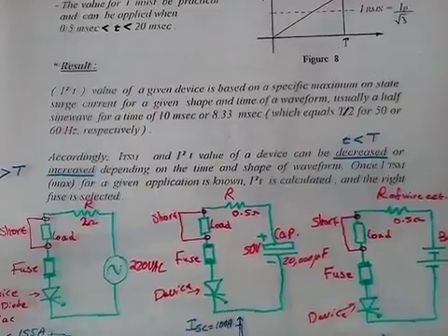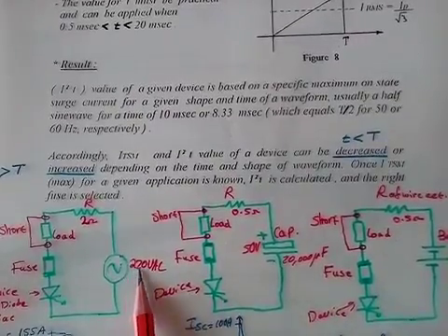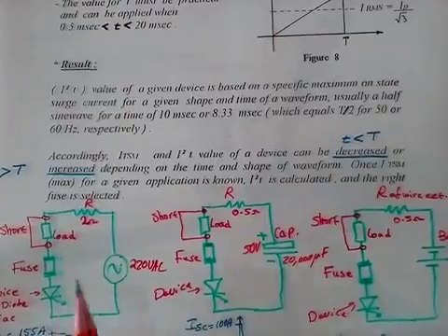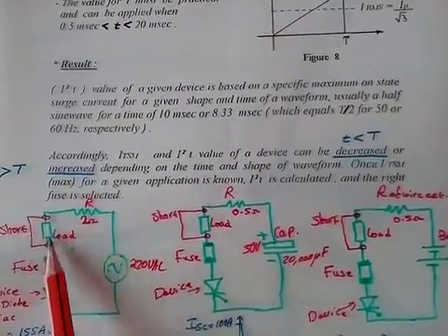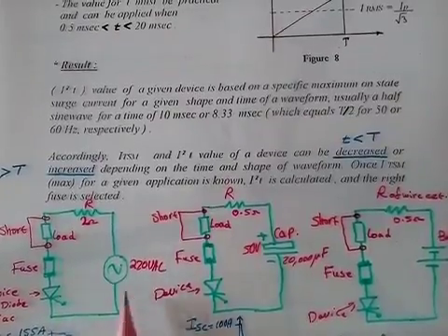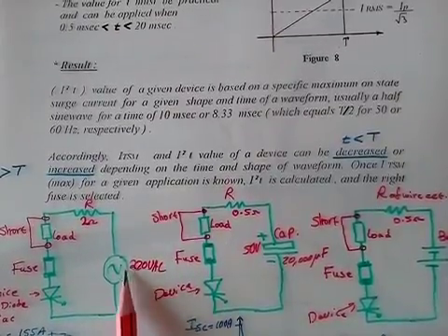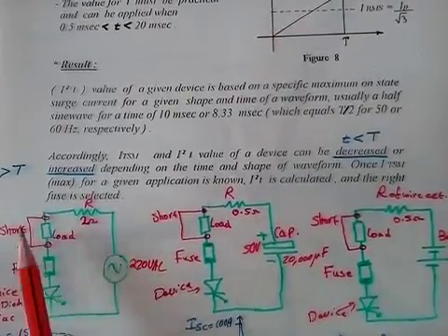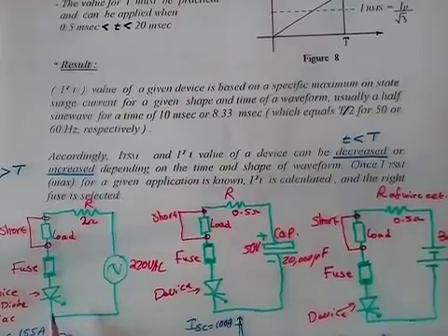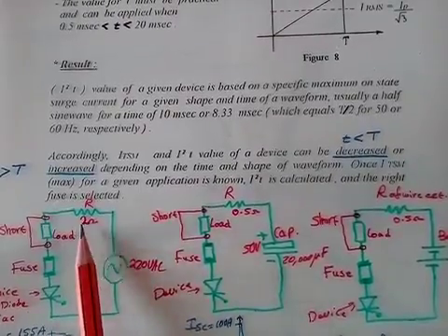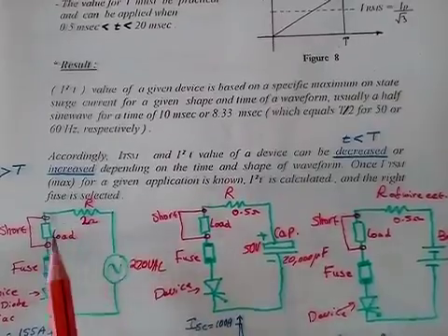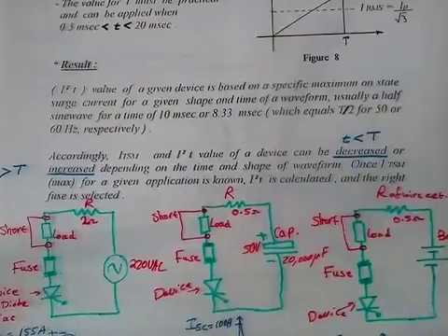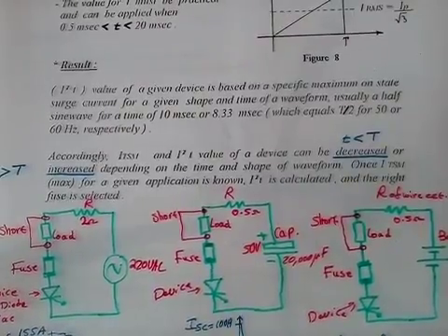Here's a few examples. Suppose you are operating on 220 VAC, and you have that surge mode up to 155 amps, and you created a short in here. Of course, you have that 155 because you divided the peak, which is about 310 volts, by the 2 ohms in here, neglecting the resistance of the wires, even though it should be considered. Or let's consider that the resistance of the wires is 2 ohms in this case. So you have 155 amps as a surge current, and it will be in the shape of a sine wave.